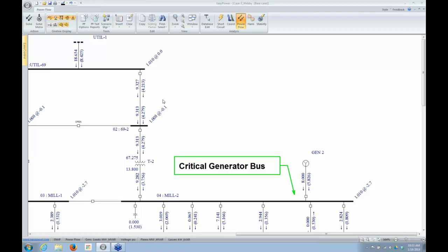Question on modeling a 200-ton chiller, 445 kVA. It's just going to be a motor load, and you're going to get the full load amps or the kVA rating for that from the chiller manufacturer. It'll be a non-standard horsepower, if it's hermetic, so you'll have to just model that as a motor. In this example, how many swings did you have? There was one swing source. You can have more than one swing source, and you can actually specify different power angles between the two swing sources. So we'll probably do an example of that when we cover an advanced session on power flow.